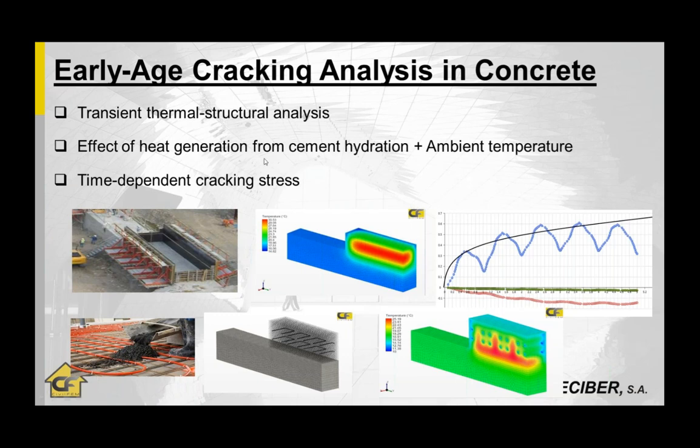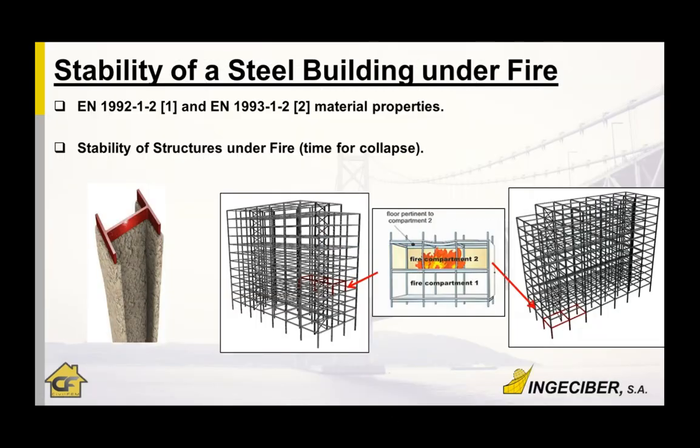Also, we are comparing with the new development tool, that is the time and temperature dependent crack stress. That crack stress is this other curve. So with this model, we can check that at these zones the thermal stresses on the concrete are over the cracking limit, and we can see in those days where the cracks develop, and find in the model those cracks developing, the same way we saw before. This is an example we can solve with CivilFEM.